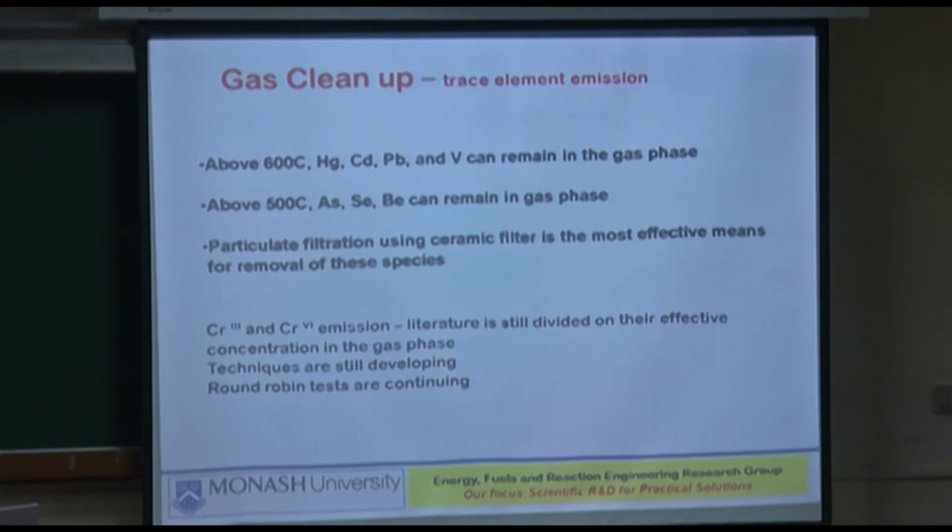So Sachin, when you do your calculations, when you do your literature review, look at that aspect. Under oxy-CFB condition, oxy-fluidized bed condition, what actually happens to this. A lot of the results have been published. Have a section on that in your literature review. I think it will be good because it will immediately tell you what not to do and what temperature to operate the subsequent cooling after the CFB. So there are some good results, and you can actually do those through equilibrium calculations.